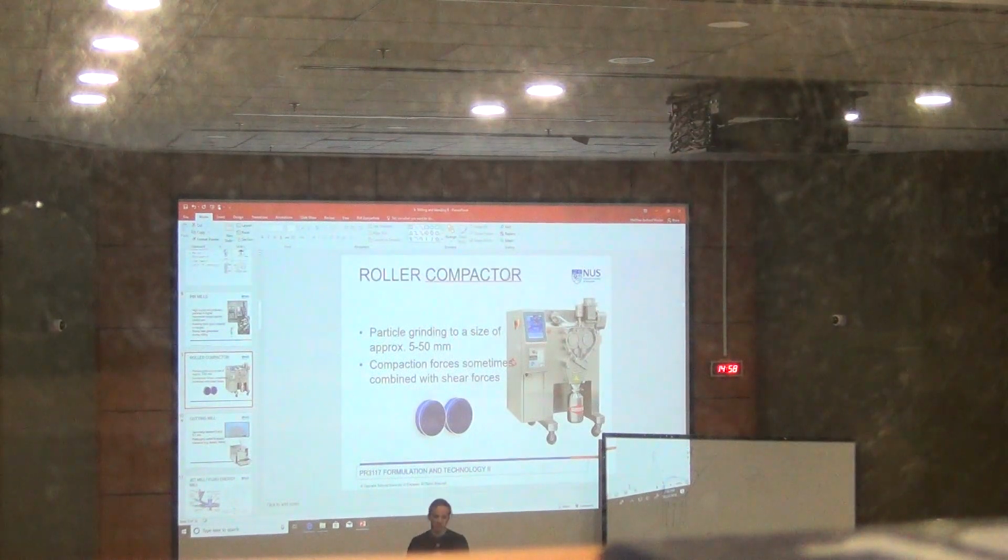Otherwise, when you take, for example, walnuts with shell completely into a ball mill, and you can mill them for, let's say, 24 hours, you will not see much. The reason is that you didn't really respect what kind of force was needed to break this structure, so that later the milling will be easier. In this case, I would advise just take a cutting mill or something if you want to really keep the shell and do not want to discard it.